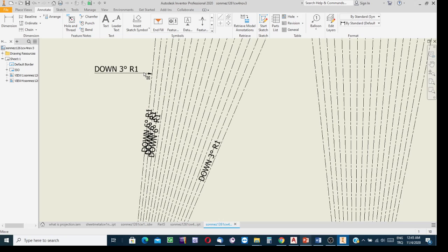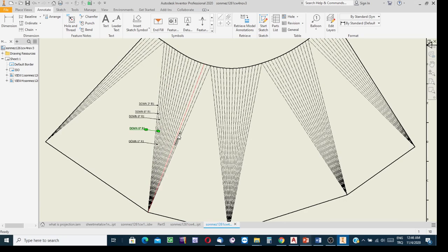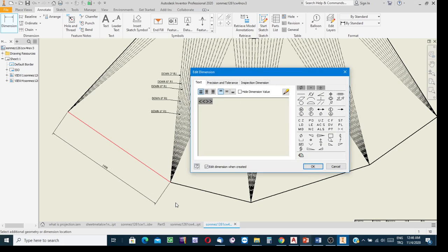You see now here I'm using the leader line technique. Hold this one from the green gripping point and then have this leader line. Yes, using such a technique, you can make the text distinguishable, readable. Okay, there will be no clash. And the dimensions, of course, show this dimension. Click on this one and then indicate this and then show this dimension.